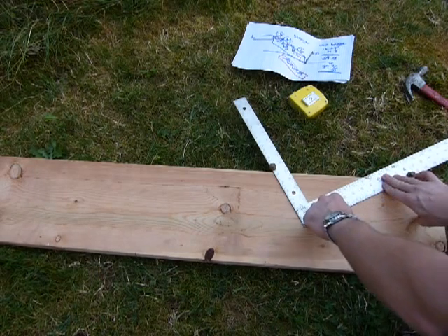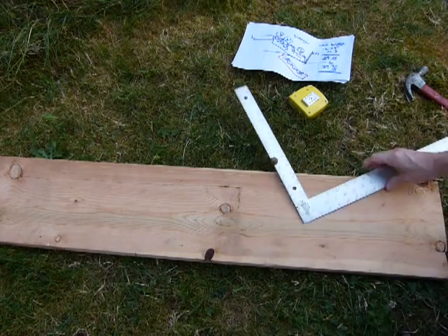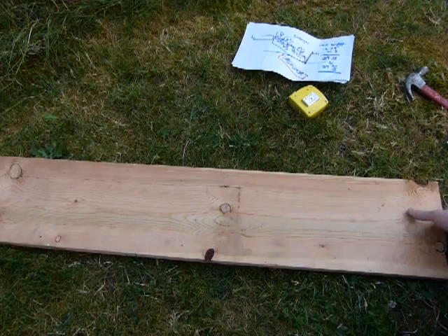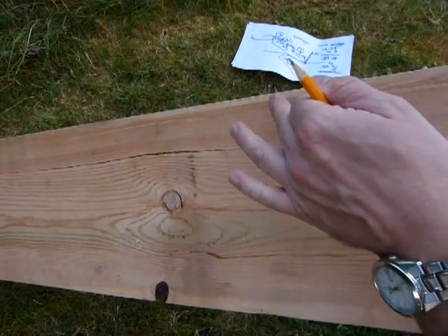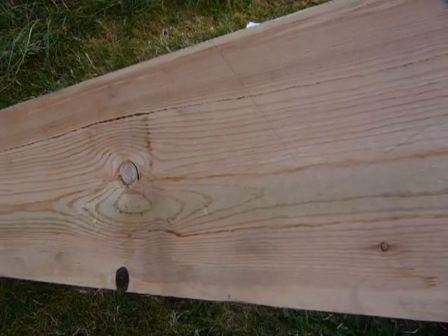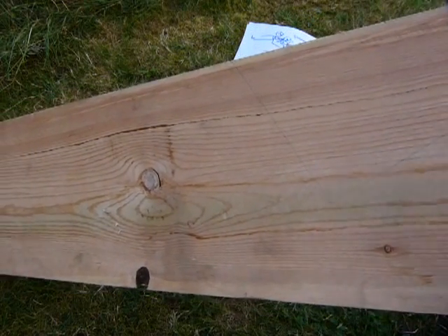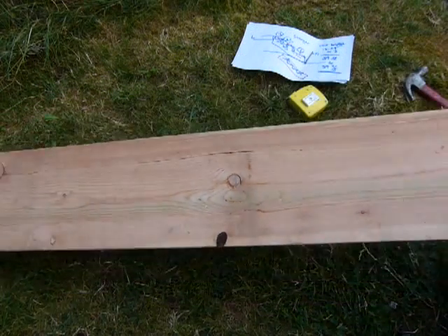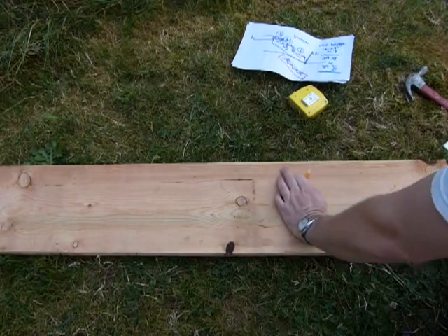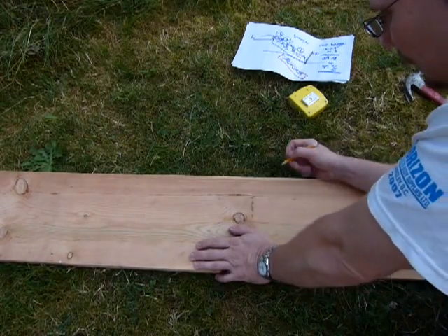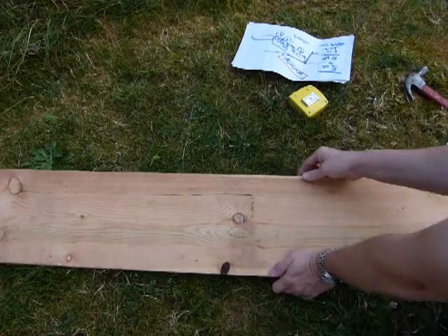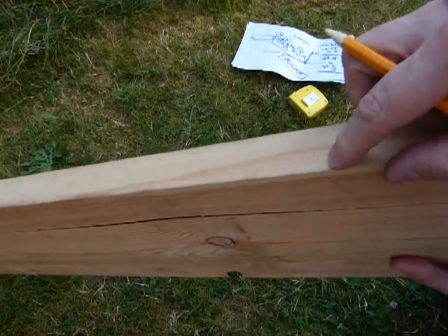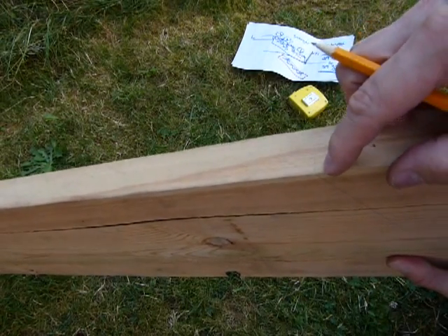I am aware that it will not be entirely visible, but I'm gonna have to do this to make the line visible. You can see the line, and when you come close enough to it, you can cut along this line with a skill saw, no problem. So that's your first one. At this point, you need to square this line across, not by eyeballing like I did.